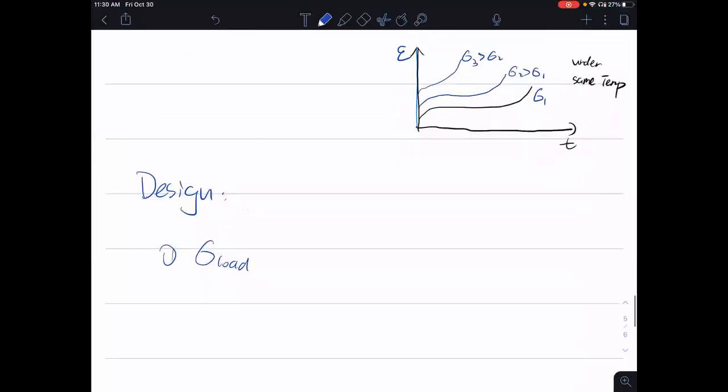Okay, so once you have that stress, you can find the stress-strain diagram, the SS curve, for different materials, right? And you can compare that stress to the yielding stress to make sure the stress you applied is less than the yielding stress.